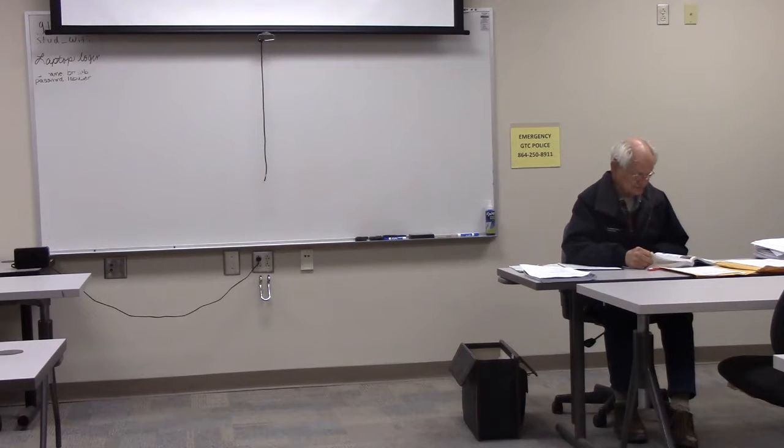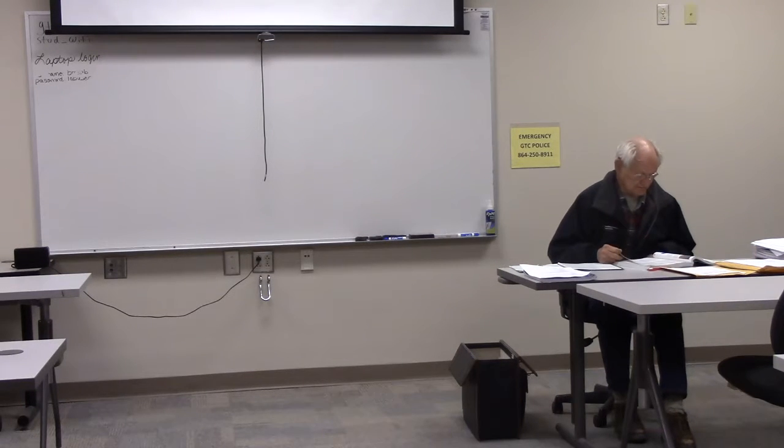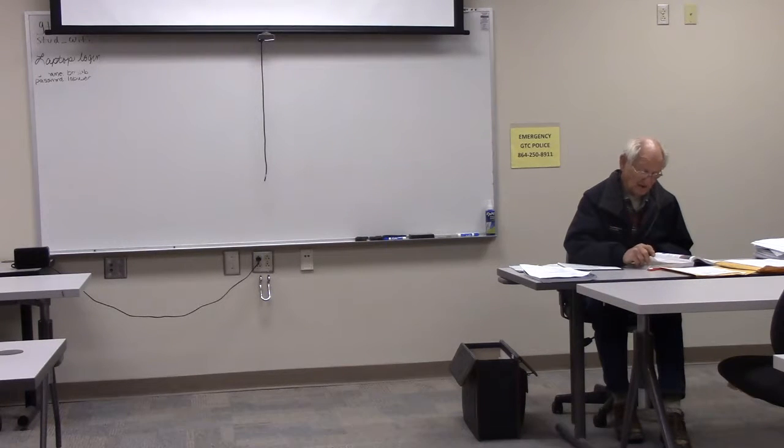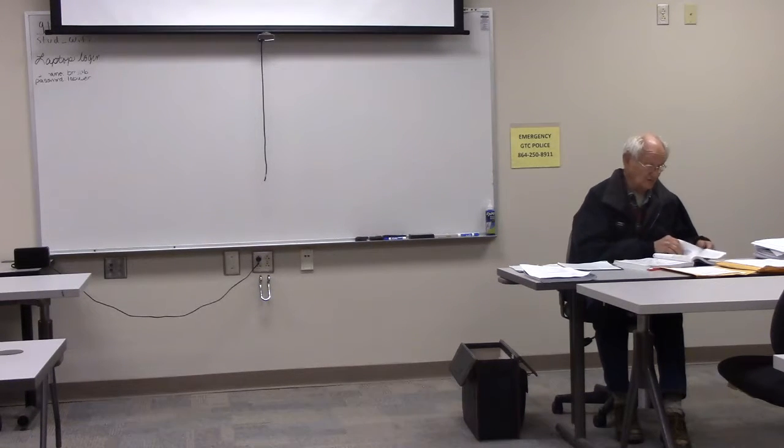Masonry boxes are used in flat slab construction jobs. These boxes consist of a sleeve with internal ears, external ears, and a plate that is attached after the sleeve is nailed to the deck. So y'all probably done some of that where you're putting floor boxes in a slab. And boxes for wet and damp weather. They make boxes that are rain tight or water tight or weatherproof.